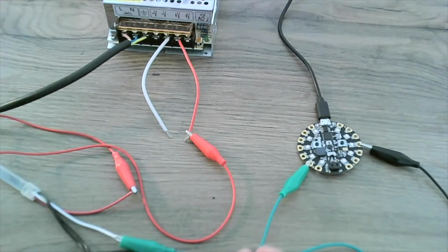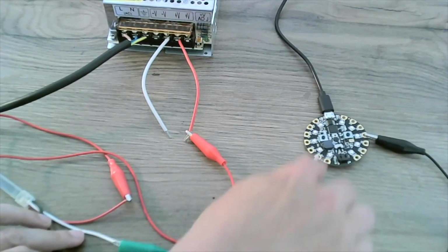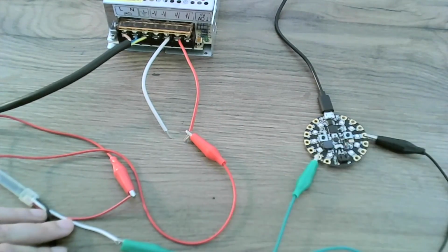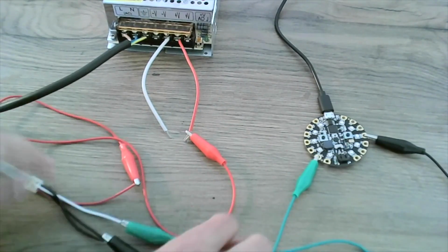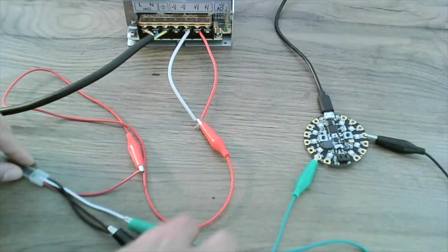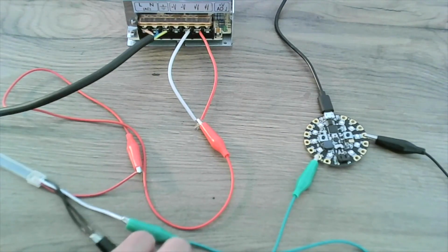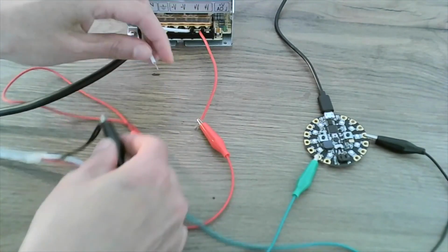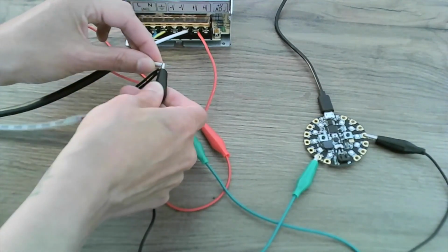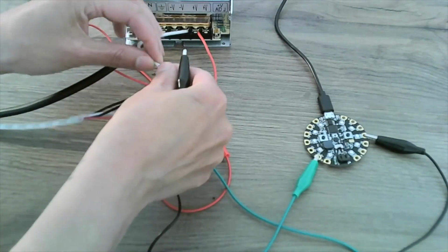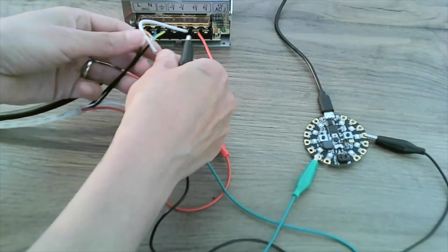We already have data connected to the data line on our LED strip. That's good, we don't need to change that. But we do need to change ground. All of the grounds need to be shared. So what we're going to do is take the end that's plugged into both of our grounds on our power strip, and we'll also connect it to our ground on our power supply. You can do this by twisting the wires and then clipping with the alligator clip.